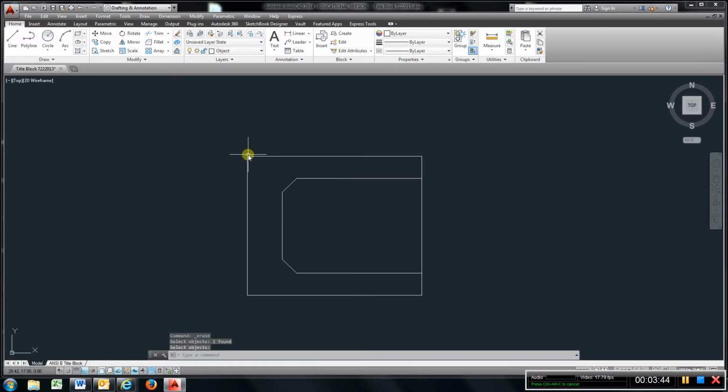Now I'm going to come to this top corner. I'm going to offset that. It tells me I go over 1/4 of an inch, so I'm going to offset 0.25. Offset 0.25, enter. This one and this one going down.